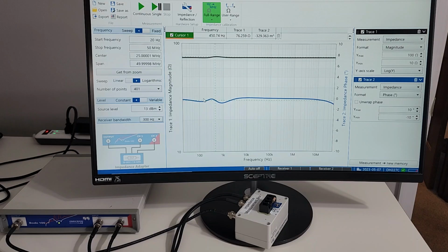Now one might ask, why is it that at high frequencies, where my inductor is above its self-resonant frequency, this impedance is still staying so well at 75 ohms? The reason is my inductor, my series RL circuit, is still acting like many thousands of ohms even by the time I'm at 50 megahertz. And my RC circuit is acting like a pretty good 75 ohms. So I put those two in parallel, and that still acts like pretty close to 75 ohms. So this circuit works very well over a very wide frequency range.